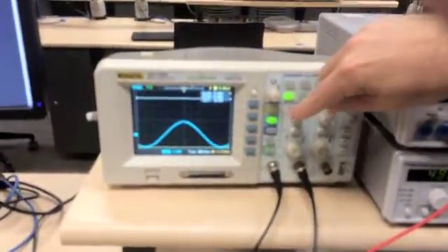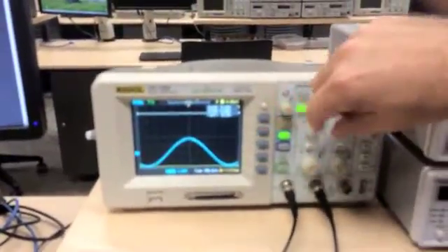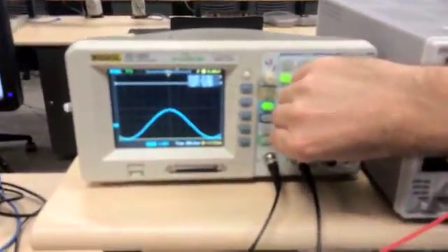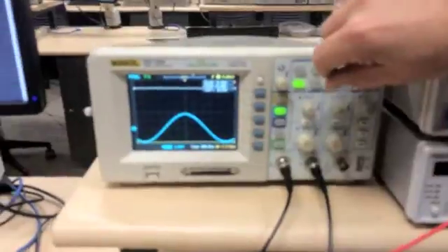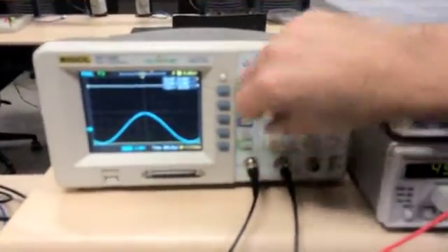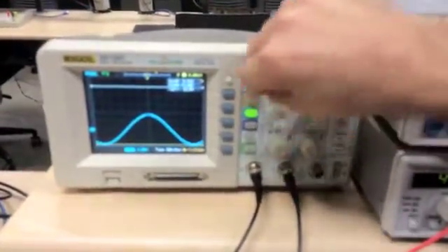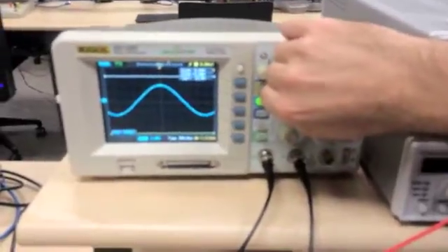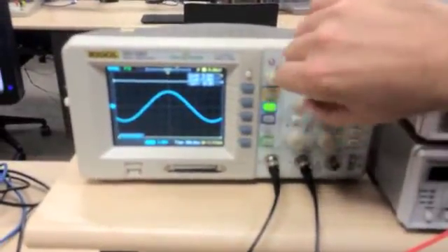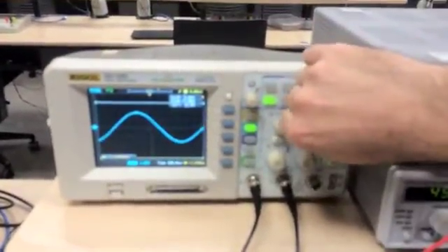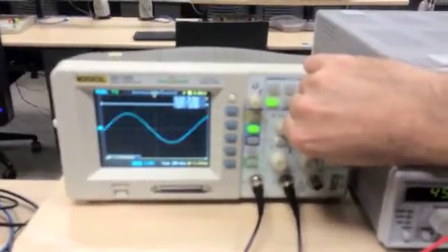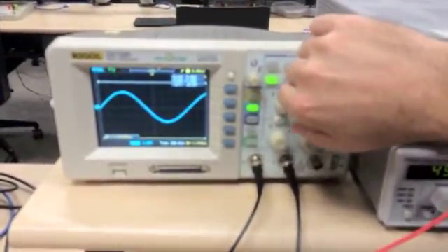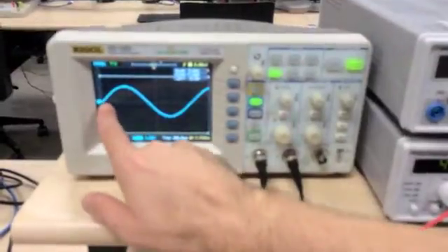On channel 2, which measures voltage drop across resistor 2, I'm interested in the period and the frequency of the voltage. So I may vertically adjust my waveform so that the 0 is zeroed, and then I have a horizontal position so that I might see where it crosses from negative to positive, and count divisions, old school. 1, 2, 3.